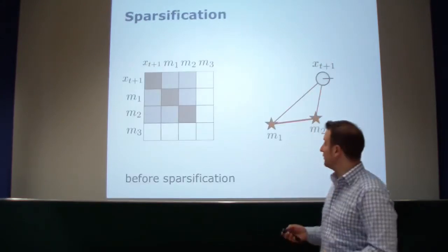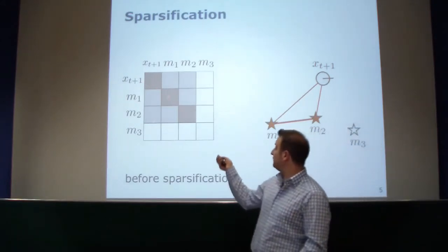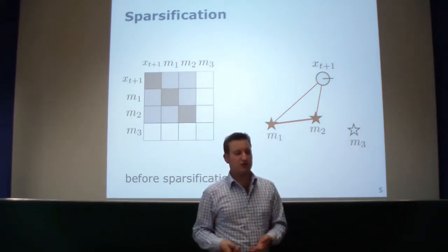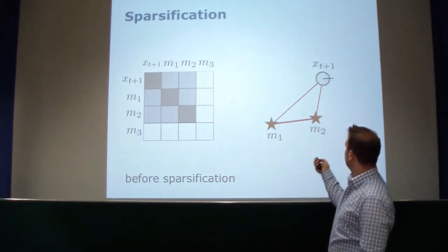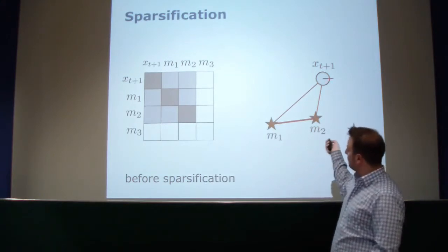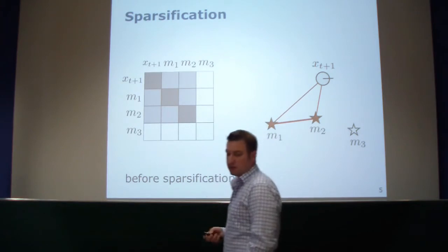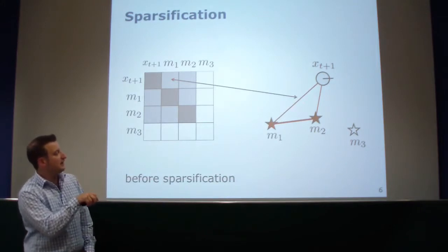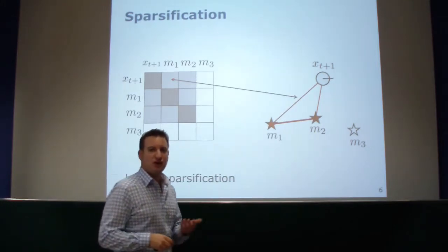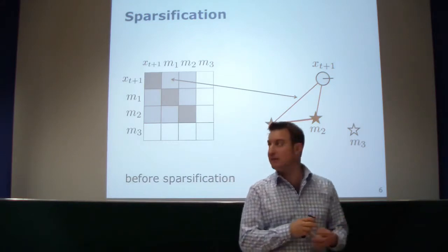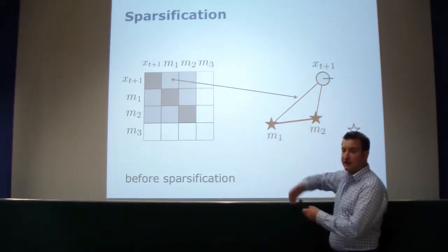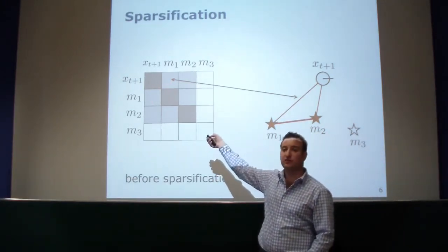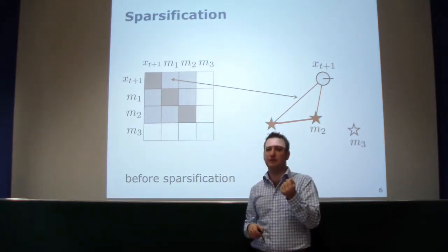So, as a small illustration, let's say we have two active features and the robot's pose, so we have this 3x3 block here in the information matrix, which is typically dense. Then due to the movement of the robot, we have elements which are typically non-zero, and this entry here corresponds to this link. If the feature M1 is now the feature that should become passive, I need to actually get rid of this link over here. If I want to eliminate this link, it means that these two values in this matrix should become 0, so there's no direct link between them.